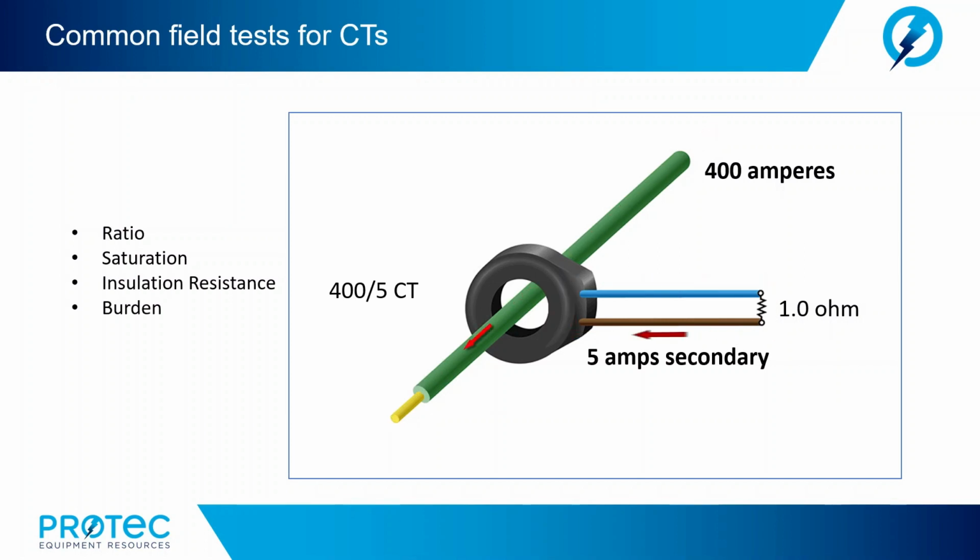However, if the CTs have been tested in the past and properly documented, there isn't much chance that the polarity is going to change. The burden test is another story. Considering the problems an overburdened instrument transformer can cause, the burden test should always be considered during maintenance testing. Unfortunately, this important test is neglected even during acceptance testing.